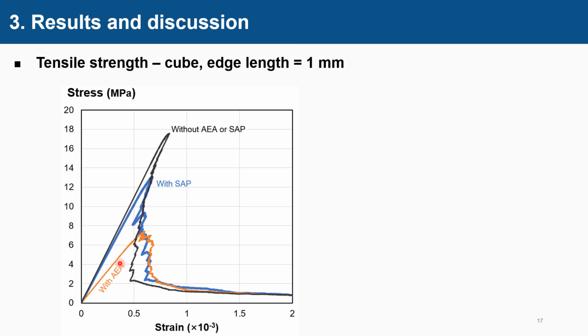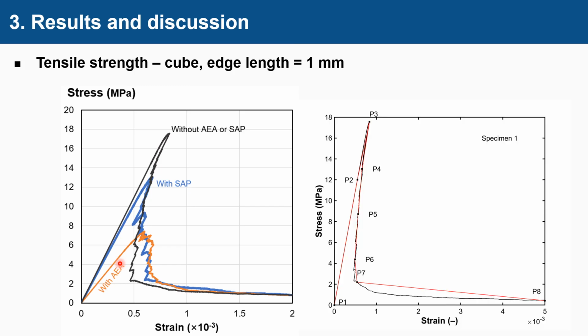The stress-strain curves are going to be used as input for the larger model, but as they contain too much information, the curves are simplified into multiple segments. That means for the larger model, a lattice beam will have a strength of P2 at the beginning, and when its stress reaches P2, its strength will become P3, etc.